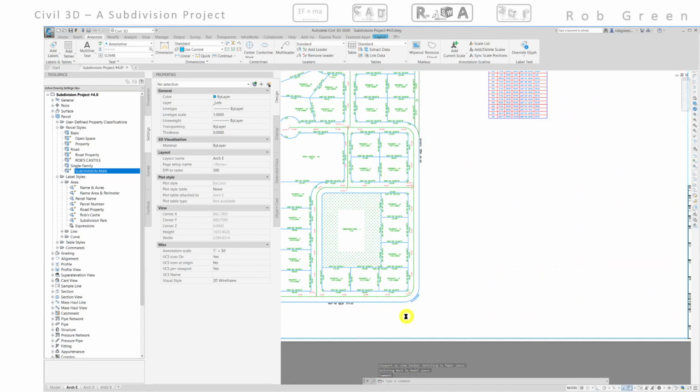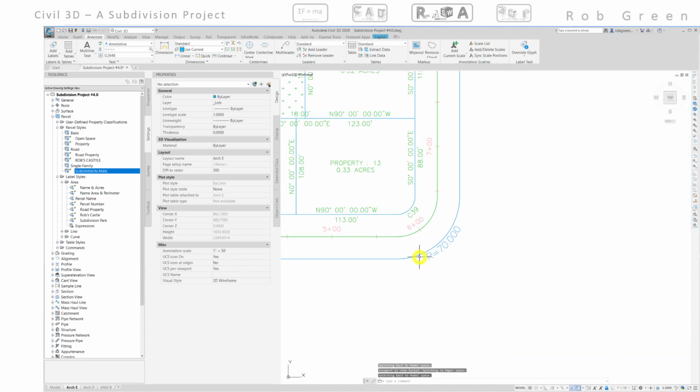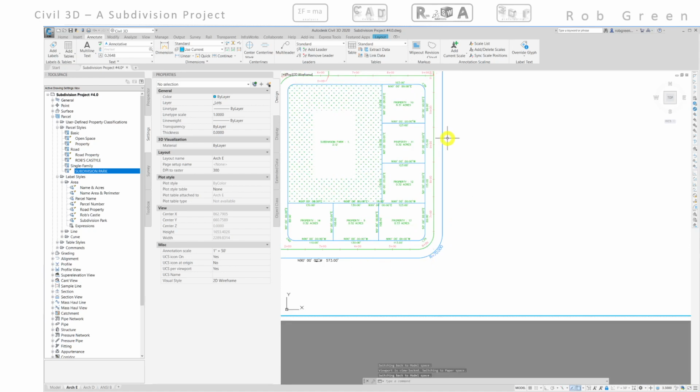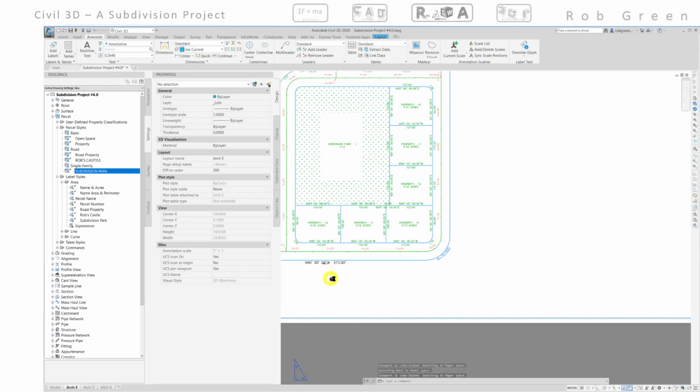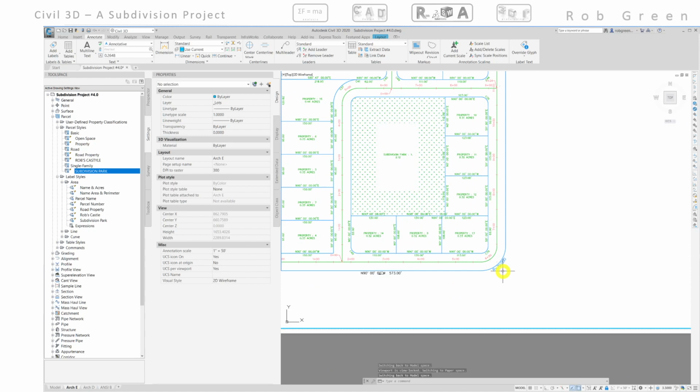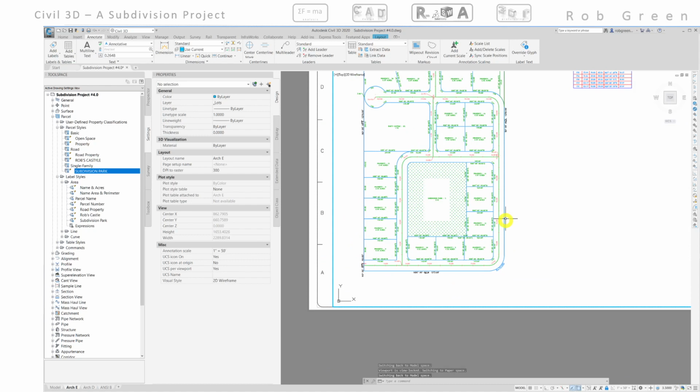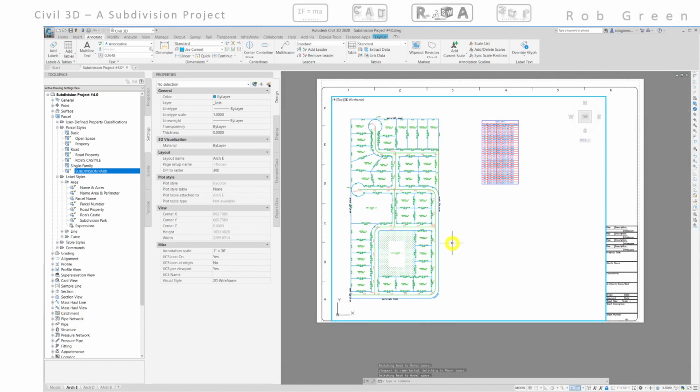What's really nice is remember that last outside radius we added, we very specifically selected a different curve style because I don't want that buried in a table. This is part of the overall outside perimeter of my land, and I wanted that radius right where it is. And that's the value of knowing exactly what type of labels we've selected.